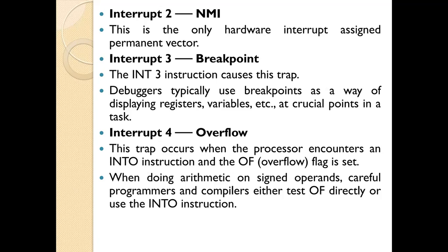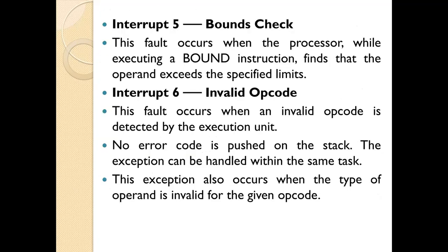So interrupt 4 is for the overflow flag. Whenever an overflow occurs, at that time interrupt 4 is evoked. When doing arithmetic on signed operands, careful programmers and compilers either test the overflow flag directly or use the INTO instruction.